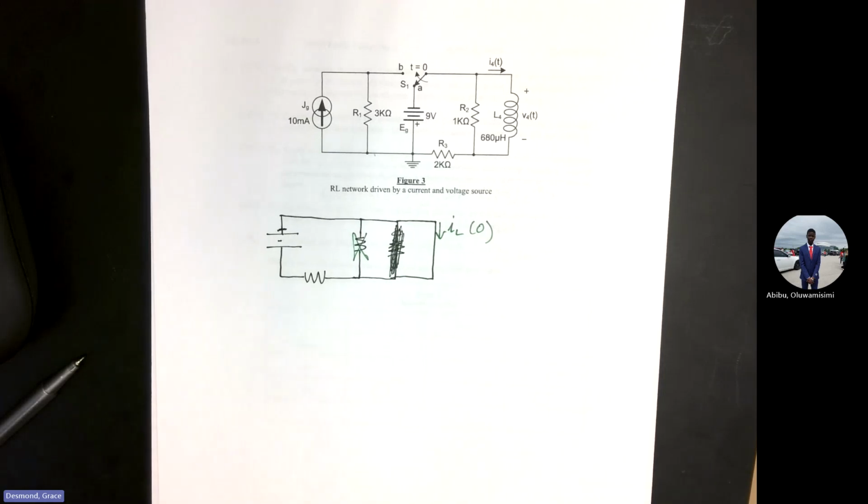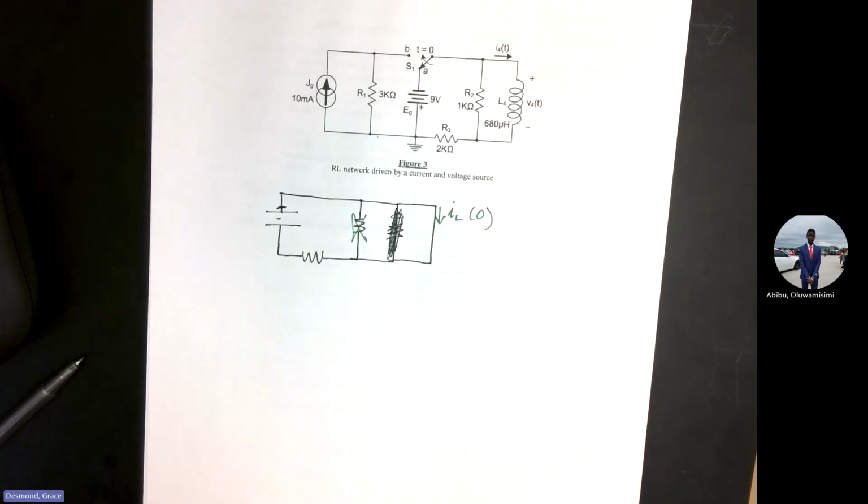I was saying this the other day because I didn't really even think about it. If you ever see a wire in parallel with anything, it's going to go away, even if the inductor was never there. If you see a wire in parallel with a resistor or a current source, it goes away. Shorting over a battery is bad, I think Turner has drilled in your head: don't short a battery.